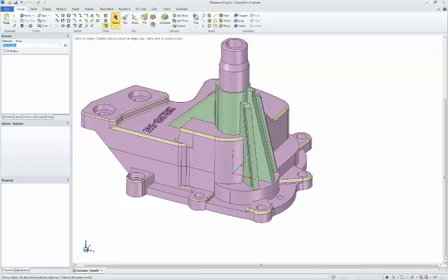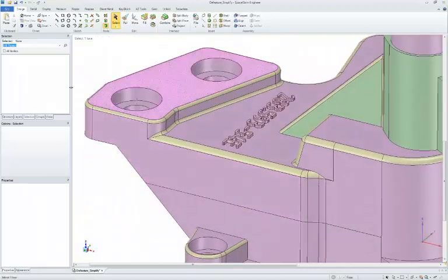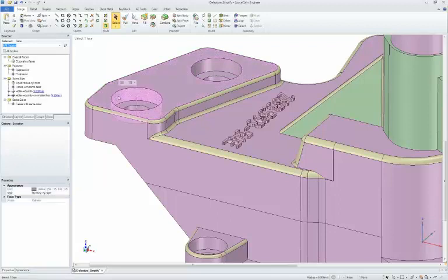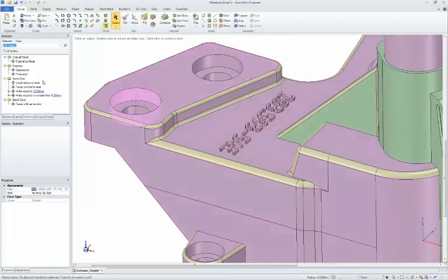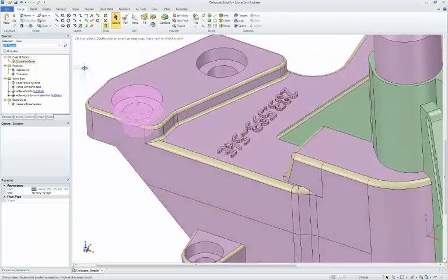How does the Find and Select tool, quote-unquote, know what you're looking for? Faces, small holes, or other things? That's a really good question. So what we've tried to do is use this selection panel, and what you select on is basically what it searches for. So notice selecting on this face here, it found me an equal radius cylinder, which is this one. It found me a face of the same area. It's that same face over there. It found me a depression. It thinks both of these two faces together are a depression. These three faces here are coaxial faces. So it selected all three of those faces.